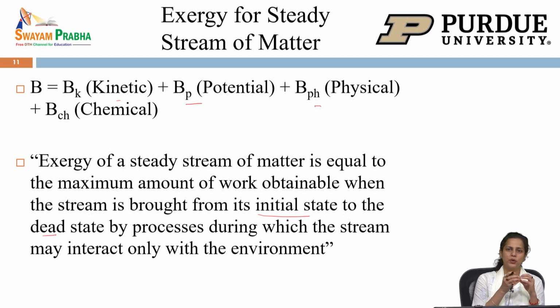What it means is that when we are preparing a stream that is entering our LCA system or processes, we are doing some work, and that work is the exergy. It is calculated in the reverse form by saying that if I have to bring this stream back into the dead state, which is in equilibrium with the environment, how much work I need to do or how much work has been done, and that is the available energy or exergy. When we calculate that, indirectly we are saying that this is the amount of available energy or work we need to do to prepare the stream for our system, and that is the quantification using the second law of thermodynamics metric for the process.